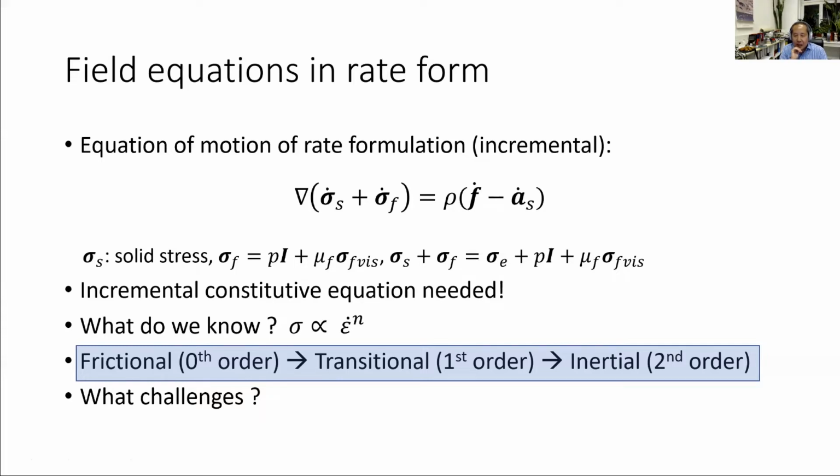The first is, what do we know about the material behavior? Because the starting point when you want to work on a model is to see how the material behaves. We know quite a lot about soil. We know very little about the debris material. And we have a look at it. There are some facts, right? The facts check. Our model should be in a position to reproduce these facts or observations. But in general, I put here in the next line a summary of the material behavior. You just consider maybe the stress as a function of the strain rate. I put the stress and the strain rate.